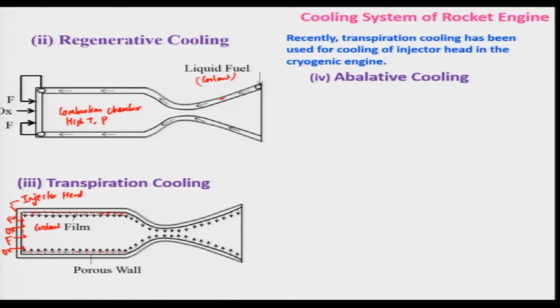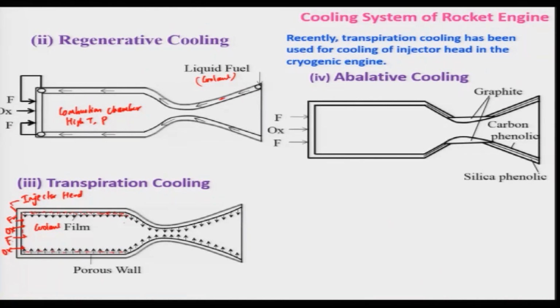So, we will be looking at ablative cooling. In ablative cooling, generally some materials are used in the throat region of the nozzle such that they can be vaporized whenever the heat is transferred to them, and it keeps the wall at a lower temperature such that it does not reach the critical temperature of melting or erosion. And in the process, this ablative material will also erode minimally,